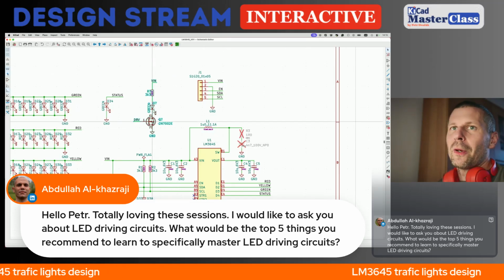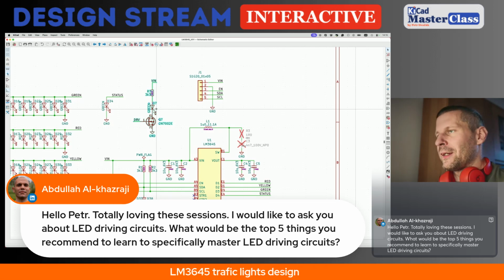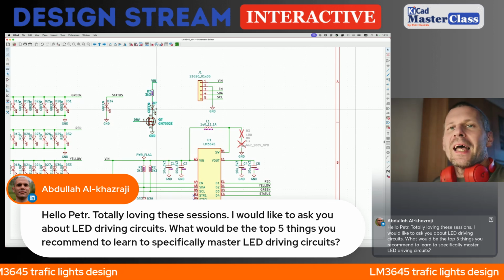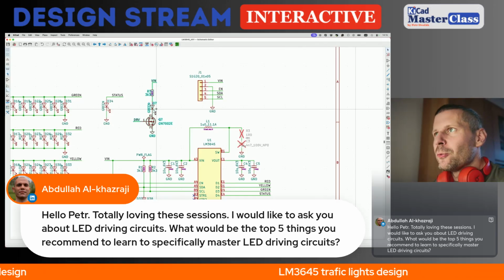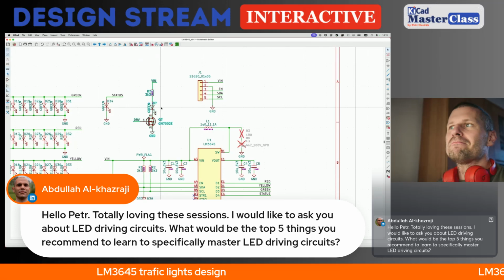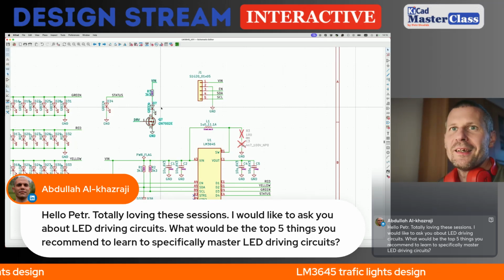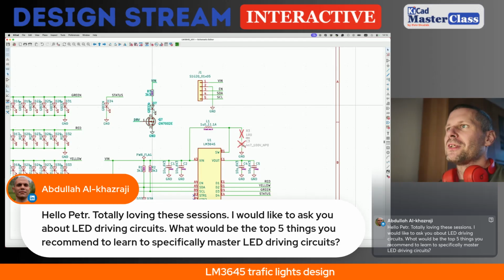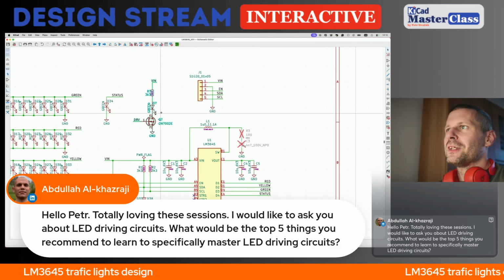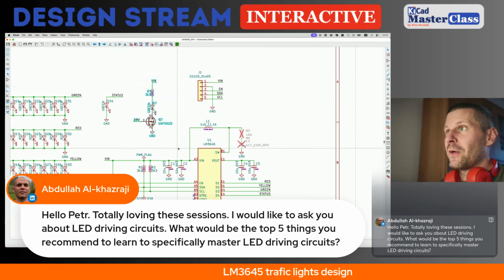I don't recommend driving directly any LED from the MCU port or any logic device. Why? Simply said, to protect the MCU port or any logic device port. The LED can be harmful, can be deadly when damaged, and then your sensitive input logic devices can be damaged easily. So I recommend using similar switches like this one.